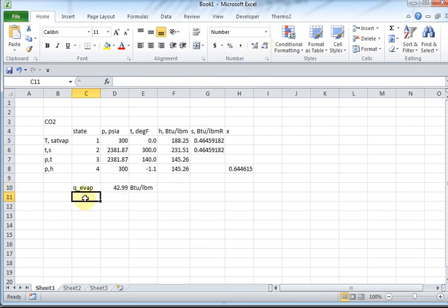All right. Now, how much heat per unit mass is rejected in the condenser? I know it's not condensing, but we'll call it the condenser anyway. H2 minus H3. So that's the same units, BTUs per pound. Okay, what about the work in the compressor? What's that equal to?